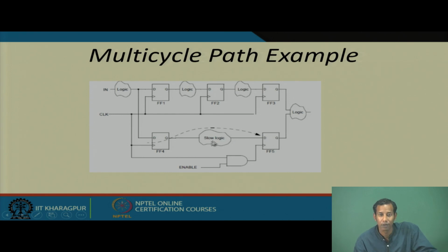So, the multiplier logic delay requirement will be much more than this full adder cell. Though the timing requirement for the other logic is much smaller, depending on this multiplier logic, the overall design cycle time will be much more reduced. So, that is why if you assign that this particular logic requires multi-cycle to complete the whole operation, at that time this path has to be considered as a multi-cycle path. Okay.